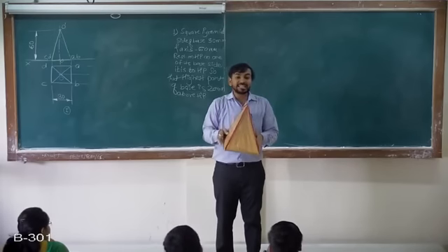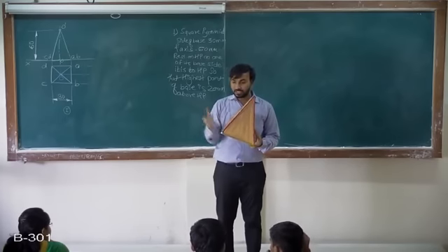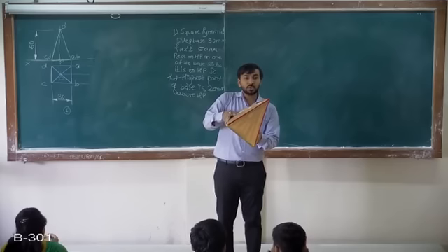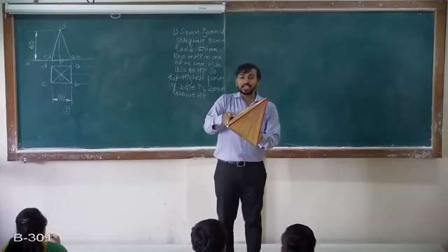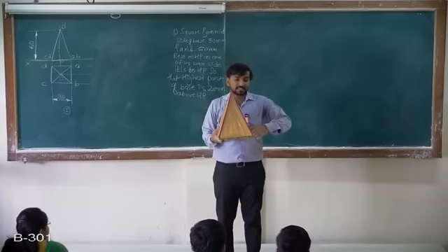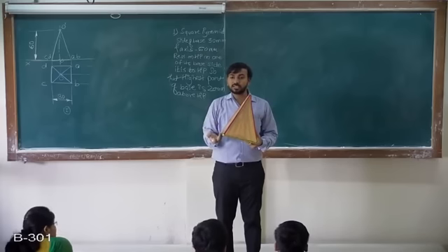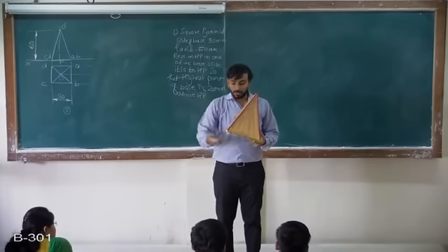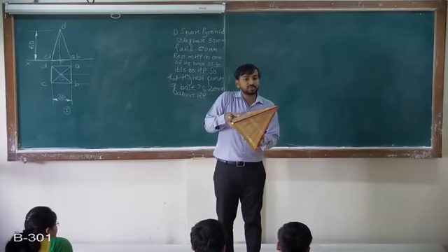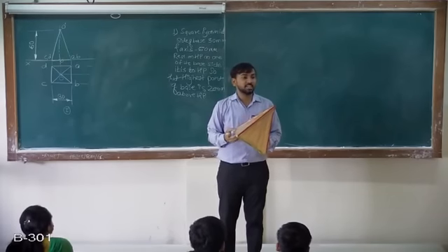So in the second condition they have given the position as a locus for this point, as you can see in the front view. So when I am going to incline to HP so that the highest point of base, as for a square, if the resting side is CD, what is the possible case for the highest point? The opposite side, always. So the opposite side is CD. So in the second stage it is inclined to HP so that the highest point, as the locus of CD is given, that is 20 mm.